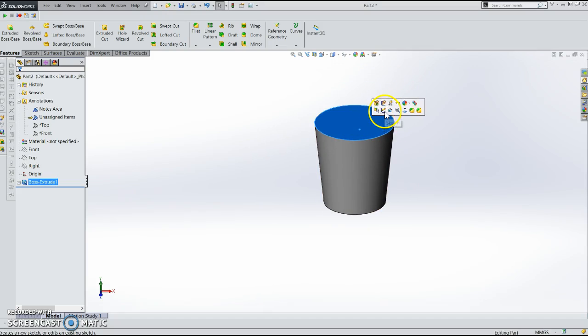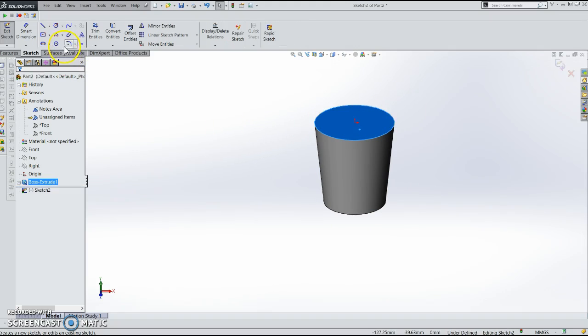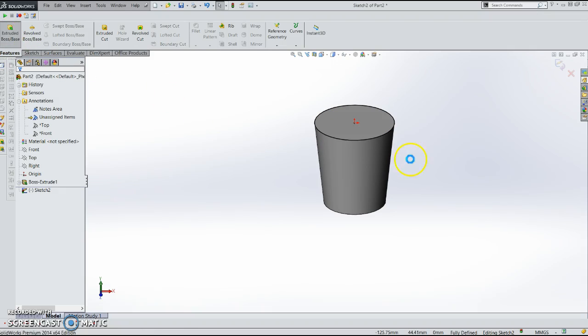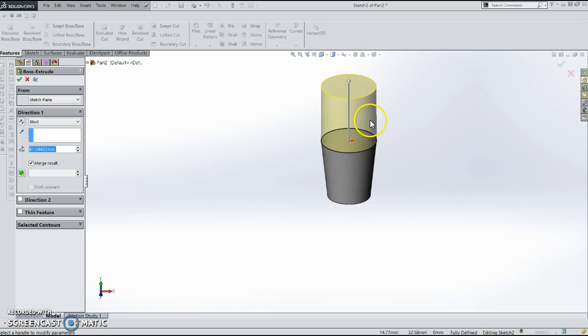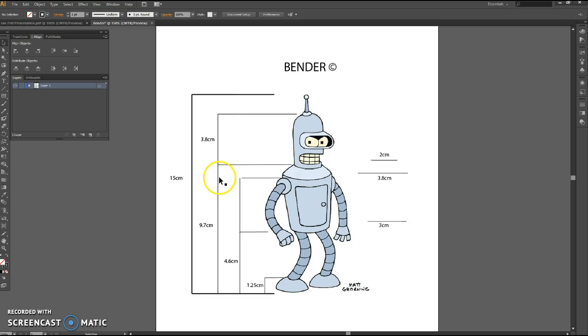Now sketch on top of this surface. I can use the Convert Entities tool, and what that does is it creates a line drawing along the entire perimeter of your surface. So from here I can use the Feature tool again, do another extrusion. And then based on the sketch, the difference between here and here, do another line quickly.